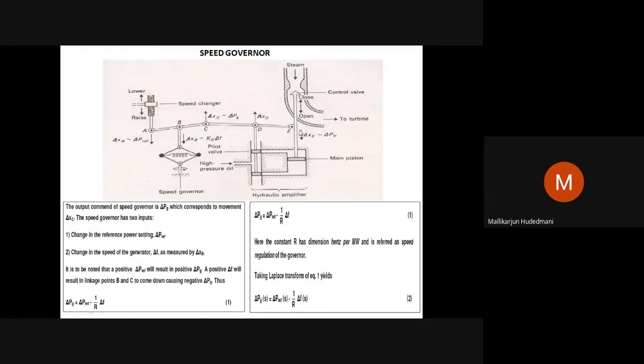So therefore, these connections, these understandings of opening of all, closing of all from the feedback network and set point network and hydraulic actuator mechanism can be connected to one another. This will be done in the next chapter. Meanwhile, I am just trying to show you that whatever the feedback speed which has fallen down is going to get reflected over here. This will shift the set point such that this feedback, which is lowering down or raising upward, will make the valve close or open in proportion to their characteristics. That is represented this way.